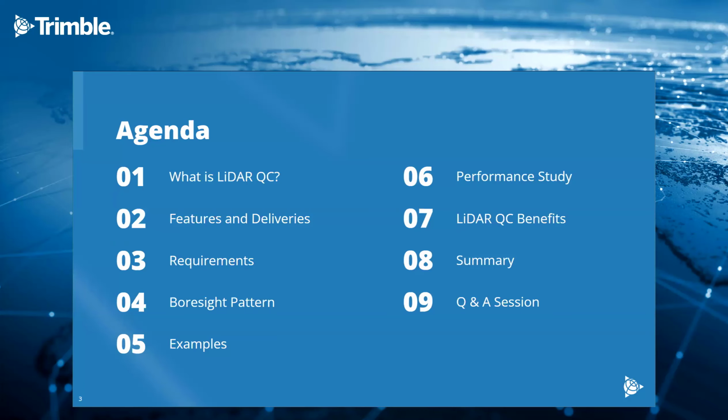Okay, so what's on our agenda today is we'll have a look at what LiDAR QC is and how it works. We'll speak about the features and the deliveries that come out of LiDAR QC. If you have a certain module you want to process data with, you have some requirements, so we'll look into this one. Boresight patterns: what are the ideal Boresight patterns when it comes to Boresight calibration happening in LiDAR QC?